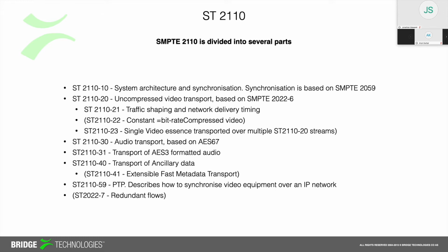And this gives you the possibility of having a completely redundant path. But what this requires at the other end is that the receivers are also across both of those feeds. What you will see on our VB440 we call the primary and secondary feeds. I've heard them often referred to out in production as the red and blue feeds.